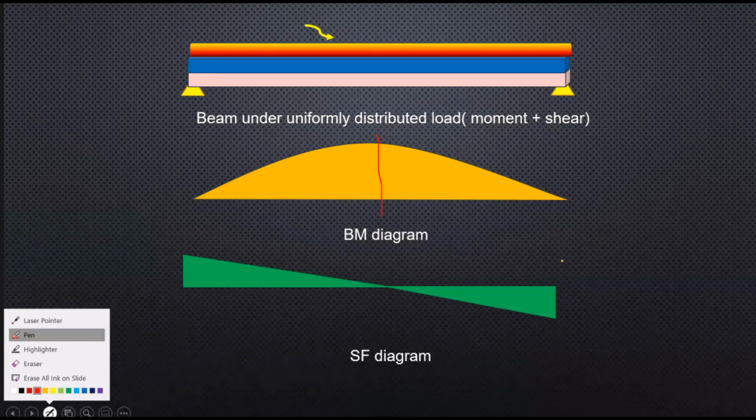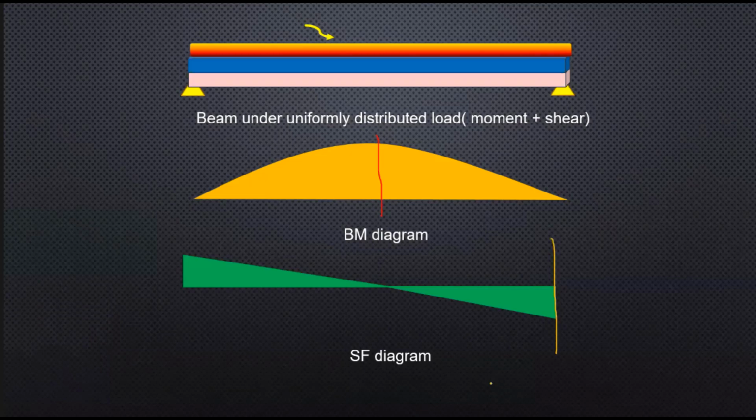So you can see the shear is maximum over here. So unlike the last time, there is no coincident shear and bending moment. The cross sections at the center are designed for the maximum bending moment, and the end cross sections also need to take the shear. So in design situations, there are two things that will come.